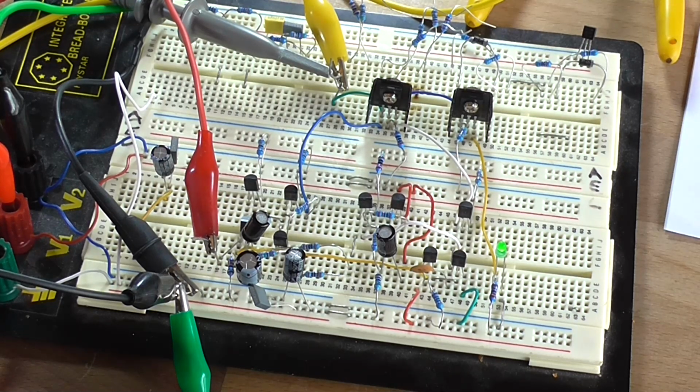But it does work with the substituted transistors, BC547, 557 respectively. However, that may affect the DC offset because of the chosen transistors' different characteristics. Also the distortion figures. He measured it at around about 0.001%, I think it was in the text there, maybe 0.0001% at 1 kilohertz at 32 ohms.